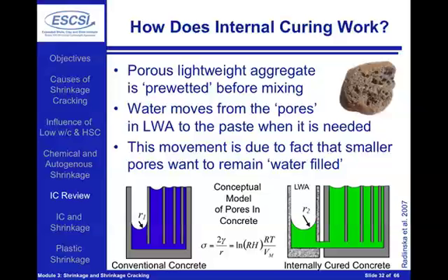If we pre-wet these, water will go into those vapor-filled spaces, and the key issue here is that the pores in the lightweight aggregate are slightly bigger than the pores that are inside of the paste. So if we look at our left-hand side on the bottom, we have a pore size distribution, an example of a pore size distribution in paste or an illustration of this. The biggest pore is empty first. So if we can place something that has water inside of it with bigger pores, water will preferentially leave the lightweight aggregate and keep the paste filled.